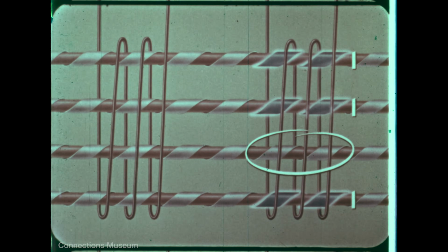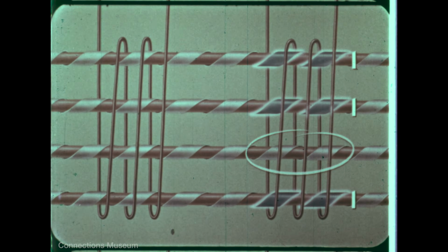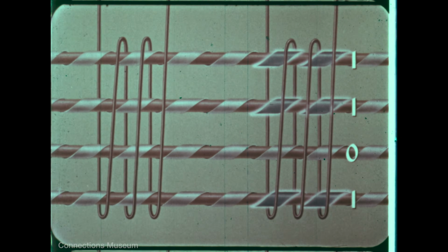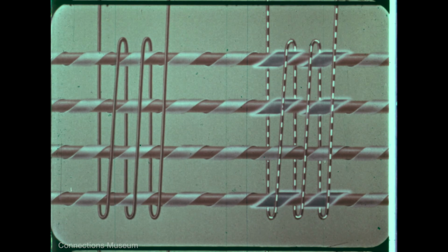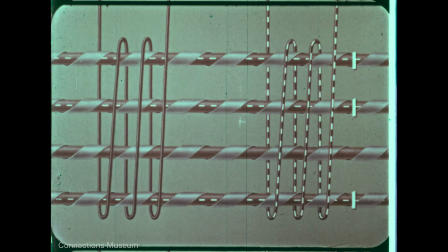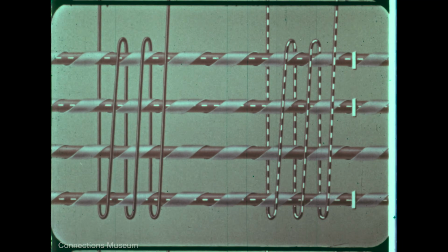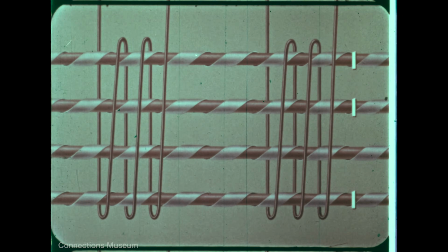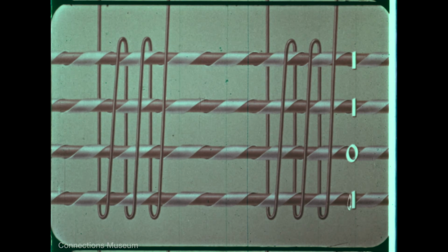Where the coil intersects an unpulsed twister, the ribbon will remain unmagnetized, representing 0. For reading, a large pulse is sent through a solenoid in the reverse direction. This reverses the flux in the ribbon where 1s are stored and causes simultaneous readout pulses on the twister wires. Absence of a readout pulse indicates that a 0 had been stored. This buffer memory has a capacity of 32 26-bit words.